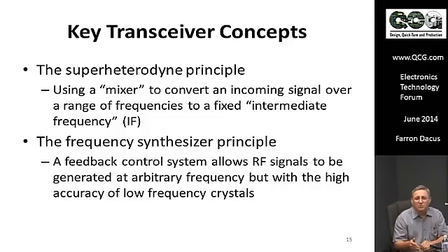And it's amazing to me, but true, that most engineers have forgotten this. If they're not RF engineers, they've seen that in one lecture, it's never mentioned again, but that is like one of the most dominant things in RF, is that noise is proportional to bandwidth, and so you're always fighting to get noise bandwidth as low as possible. And that's what a superhet does. It does it two ways.